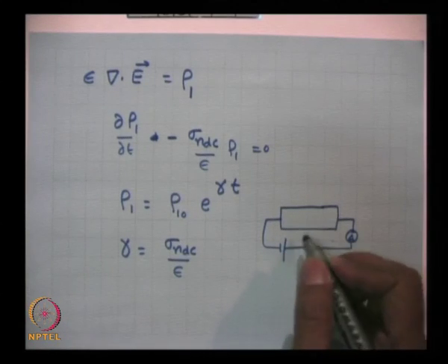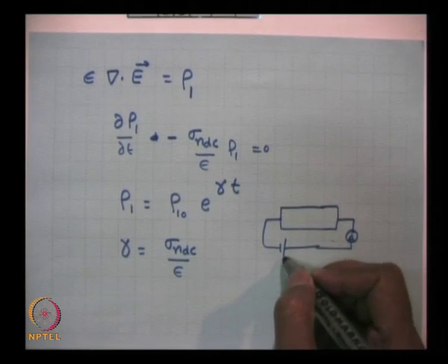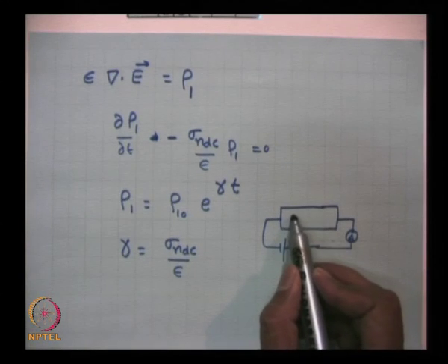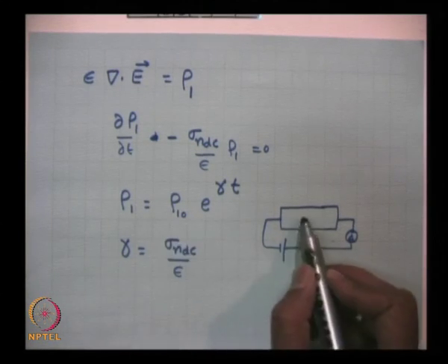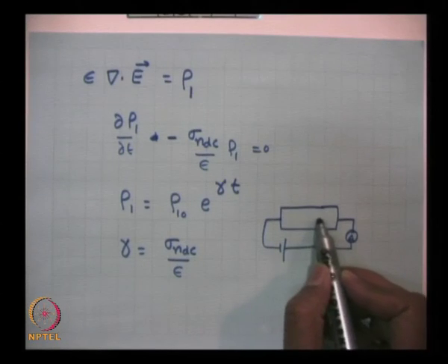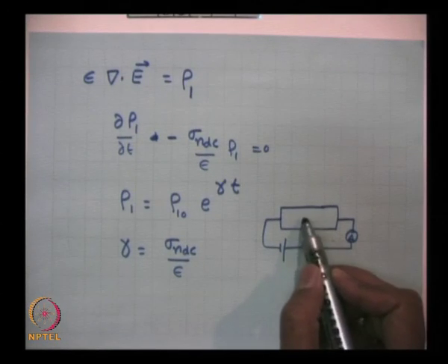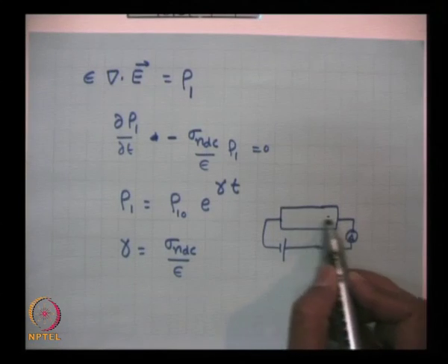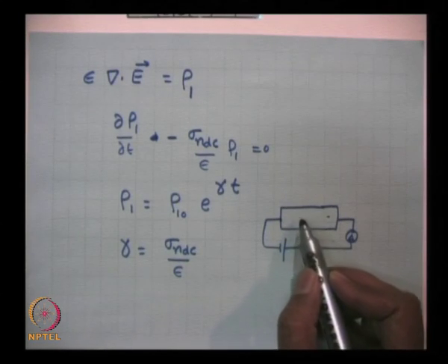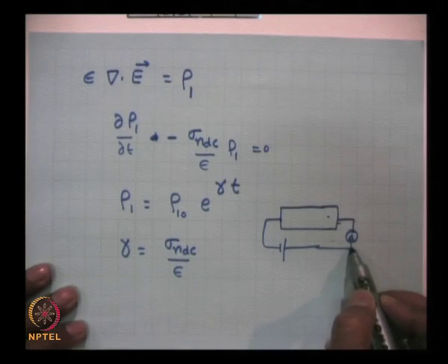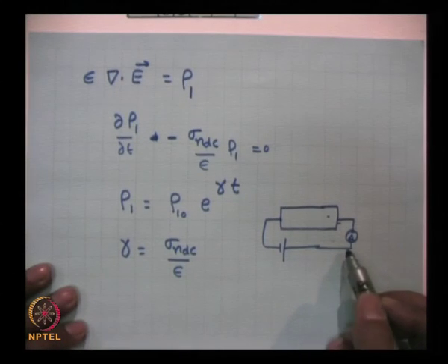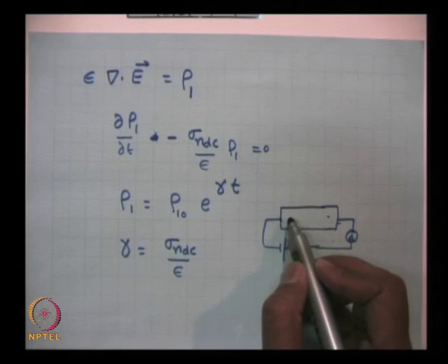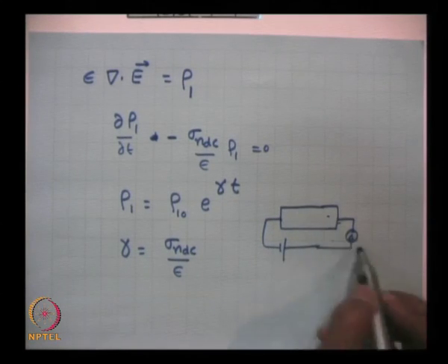So, when you apply this voltage in the negative differential conductivity region, then this high density accumulation region will move towards the end, the charge region will move, or the electrons will move in this direction. So, when the bunch of electrons comes here, suddenly there is an enhancement in current, but a sudden burst. So, some sort of electron accumulation or electron domains are created inside the semiconductor, and then you get this current up.